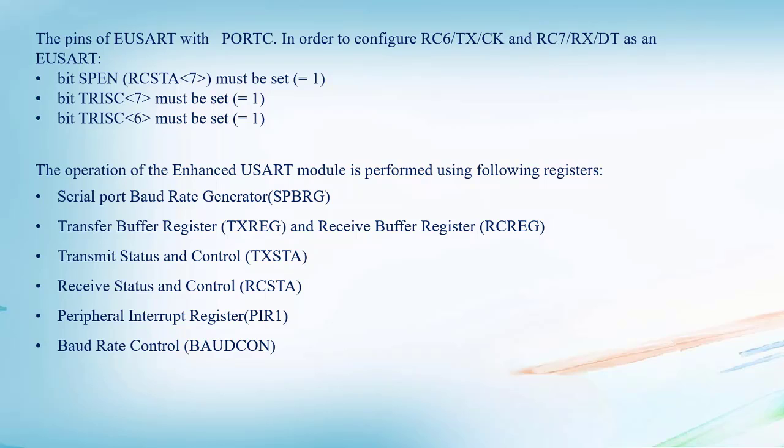RCREG. Similarly, when the bits are received serially via the RX pin, the PIC 18 deframes them by eliminating the stop and start bits, making a byte out of the data received, and then placing it in the RCREG register.